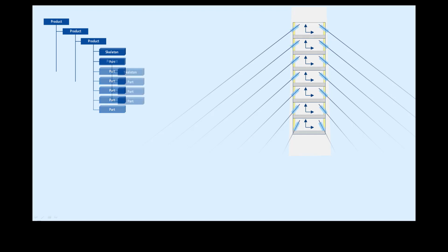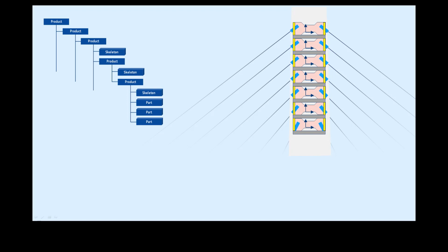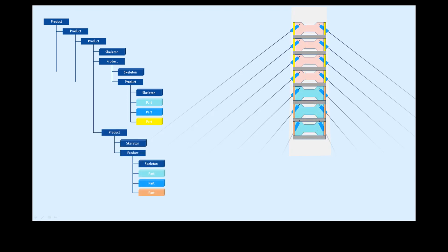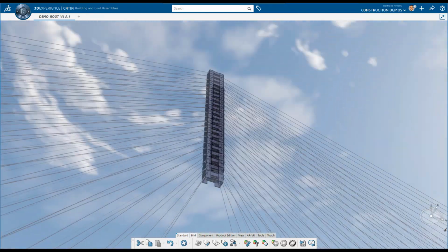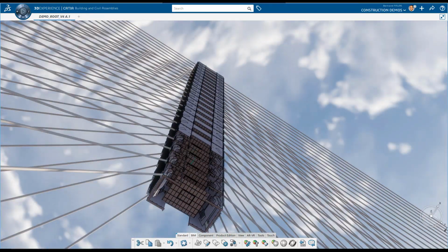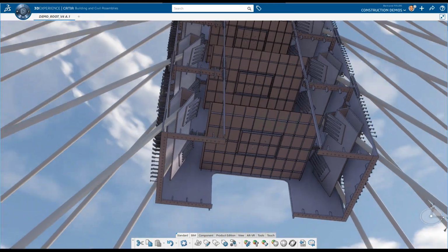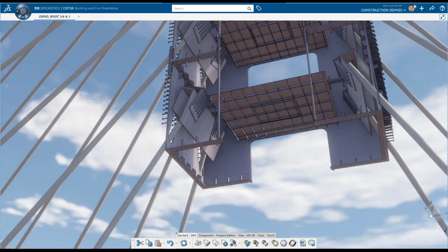This design methodology, where a part under a product drives all other parts of the assembly, is widely used and commonly known as skeleton methodology. It's convenient because you can recursively detail your model more and more and create multiple variations of your assemblies with very few different references of components, but only if they are all designed in their local axis systems.